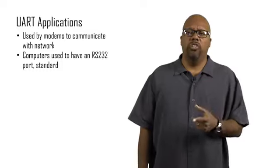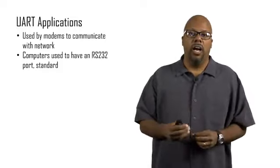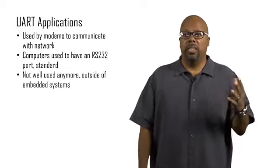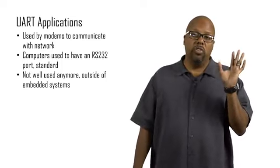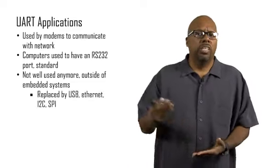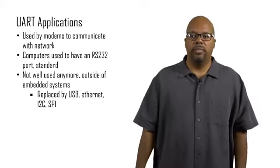Computers used to have an RS-232 port standard. RS-232 is a port made to communicate with UART. So they used to come standard. They don't do that anymore because UART has been supplanted by other better, more effective protocols nowadays. So it's not well used outside of embedded systems and IoT devices like we're dealing with. It's still used in those domains for debugging mostly. But it's been replaced by things like USB, Ethernet connections, I2C, SPI. We'll cover those later. But there are a lot of other options that you can use instead of UART nowadays.